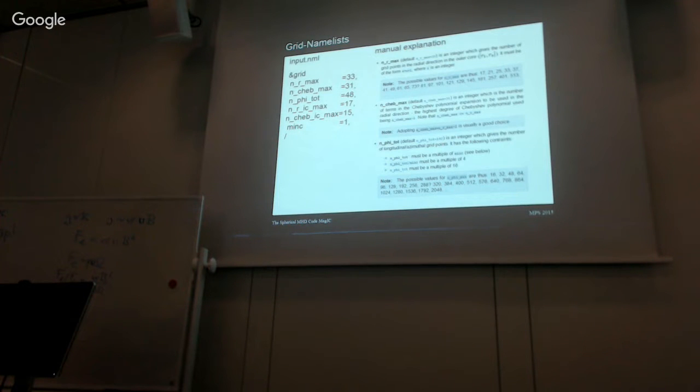And indeed, there are some solutions where you know that they have this symmetry. So very close to onset of convection, for example, they have a given azimuthal symmetry. And you can use that symmetry right away, and you save a lot of computational time. But that's only very close to onset, where everything is simple. If you crank up your Rayleigh number, you drive your system harder, everything becomes more complex. And then this typically loses applicability, but sometimes we use it nevertheless, because it saves computation.